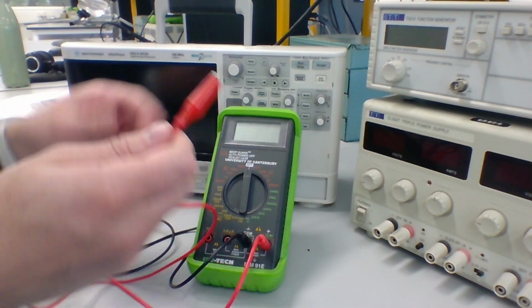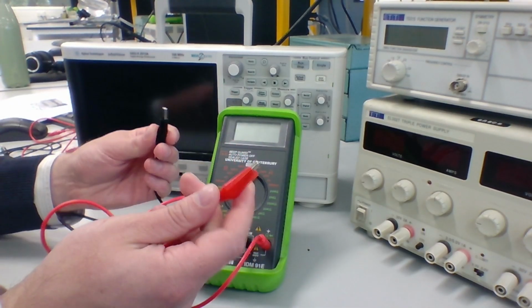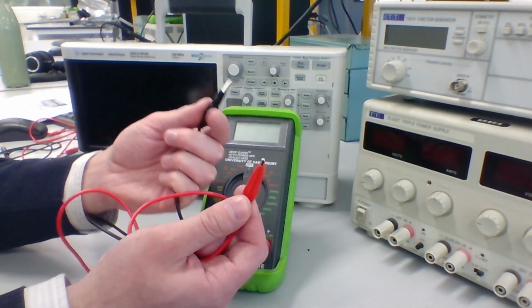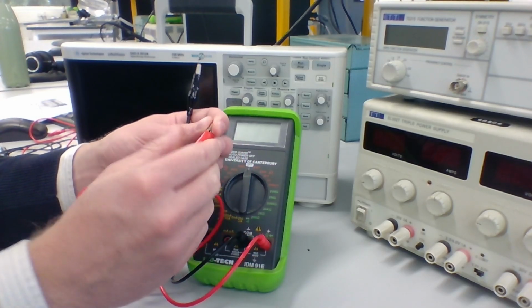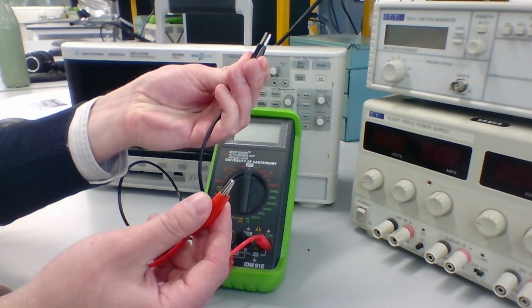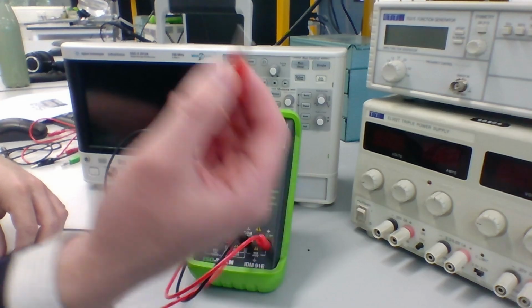Note that it is worth following the color coding on these terminals. It is not strictly necessary for this to work. Electrically, the colors do not matter, but it makes it a lot easier when you're observing your circuits. When you go to grab a multimeter, you can say, oh, right, I know the black is connected to ground, the red is connected to my actual measurement port.